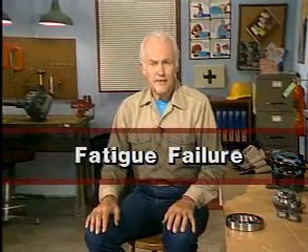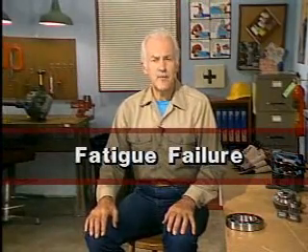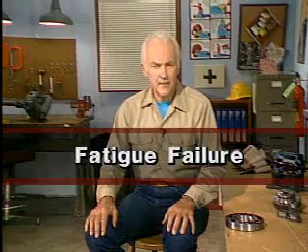All of the conditions that we just mentioned can lead to early bearing failure. And if a bearing fails, it can result in a lot of damage to the gears in the unit. One type of gear problem is gear tooth breakage. There are several ways in which a gear tooth or teeth can be broken. One way is through fatigue failure. Fatigue failure usually results from repeated bending or flexing of the gear teeth.